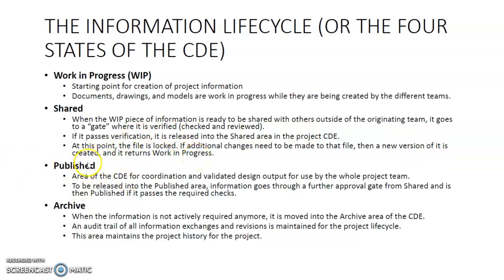The published area of the CDE is for coordination and validated design output for use by the whole project team. The information goes through a further approval gate from shared and is then published if it passes the required check.